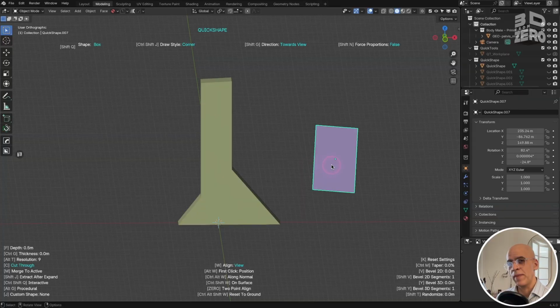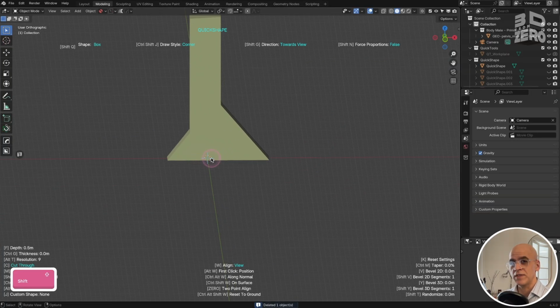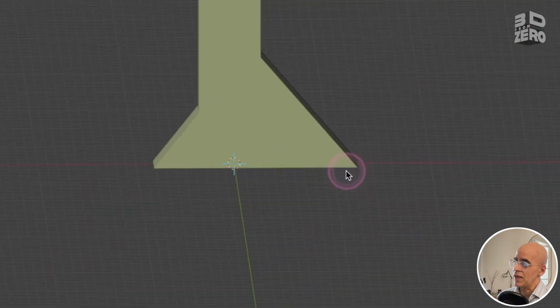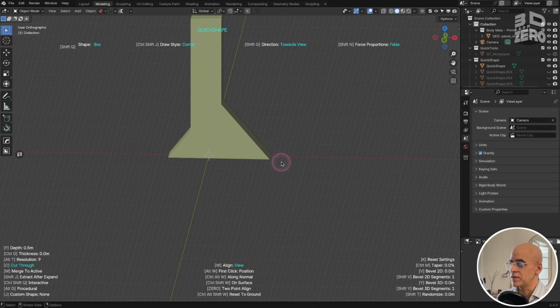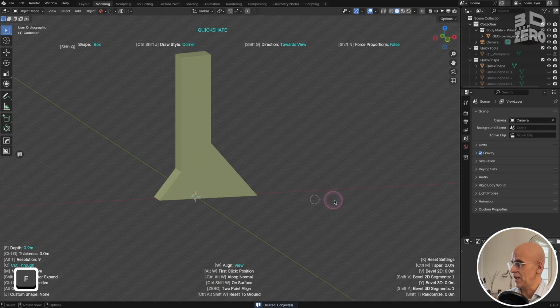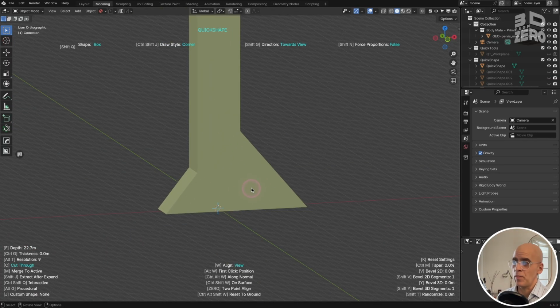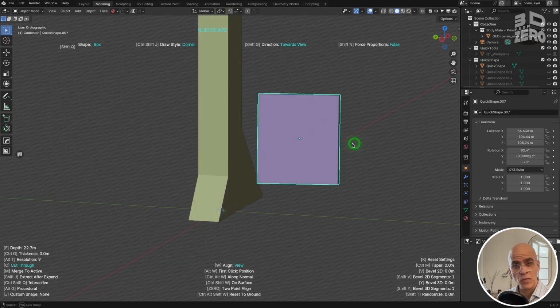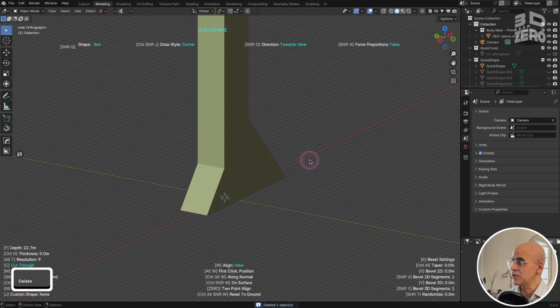So first, remember that by default, Quicktools is using two values. One is the position of the 3D cursor, and the other is the angle of your viewpoint. And it uses those two values to calculate the position and the orientation of shapes. That means that shapes and cuts are going to be made perpendicular to the surface of your monitor, really, perpendicular to where you're looking from. And it's going to do it by default level with the 3D cursor.